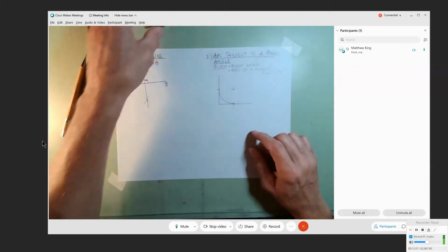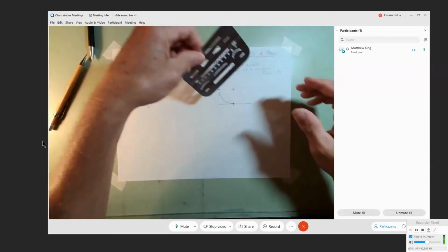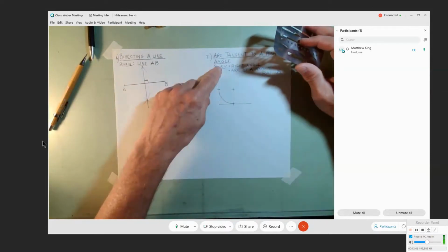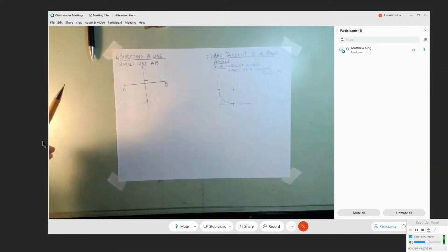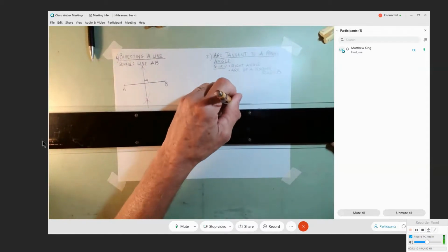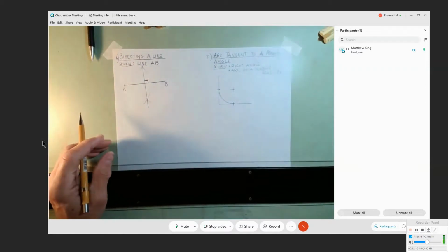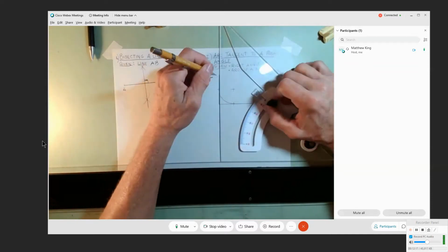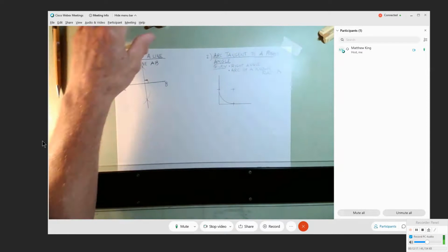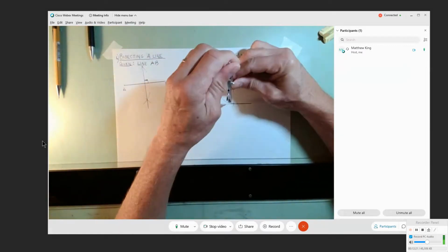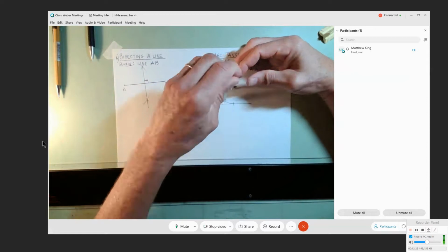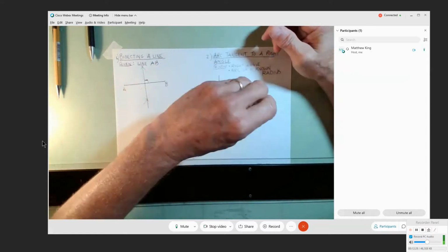Okay? So in reality, we would take our eraser shield and we would erase off the excess and wind up with that nice clean arc. And then we would go back with our pencils and darken that all up to our acceptable 0.9 millimeter thickness along with the arc. So that's always the follow-up of draw it light and then finish up with it being nice and dark. And you have to readjust your compass slightly to build out that thickness.